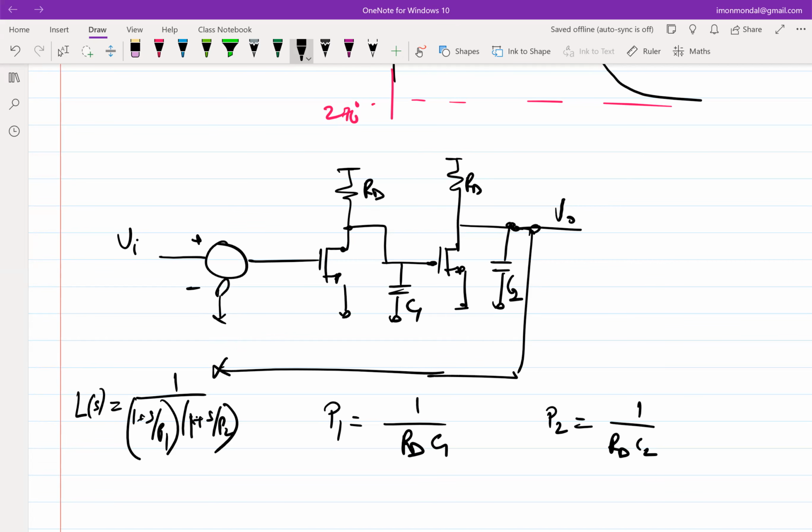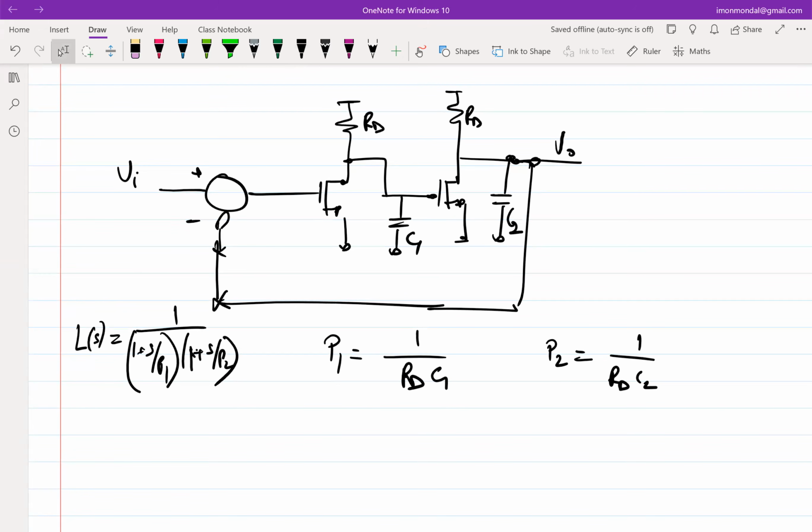And this is an open loop system in which we can figure out the poles by looking at the time constant associated with each capacitor, if possible. In this case, it's possible, so we could figure that. And then we said that P1 and P2 have to be far apart, and so on and so forth. And in order to split them, what did we do? We put an additional capacitor CC. Right? You remember last class? We put an additional capacitor to put P1 to a lower frequency.